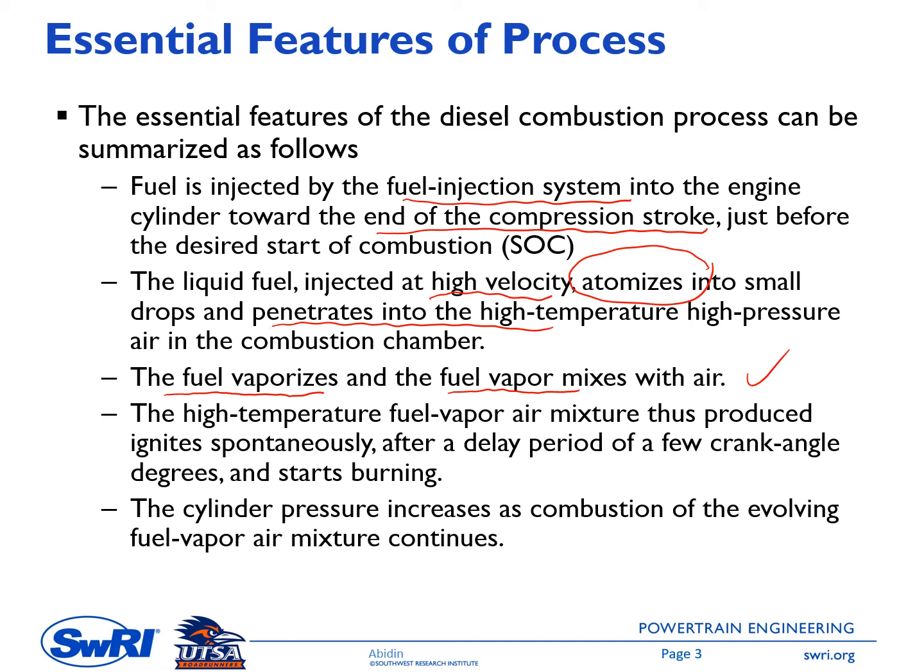And then the compression stroke further moves toward the top dead center. Then the temperature will further increase, and at some point the mixture of air and fuel vapor will ignite spontaneously.